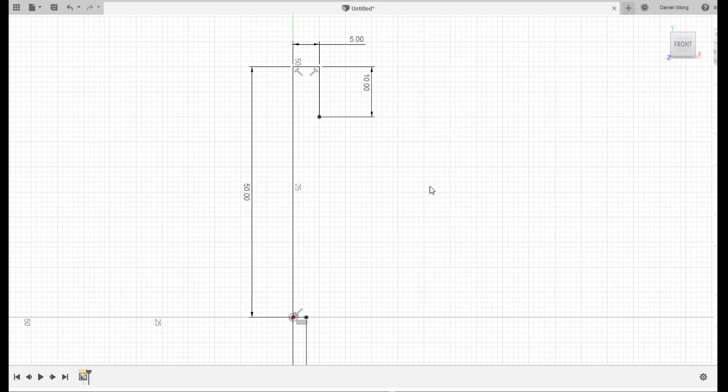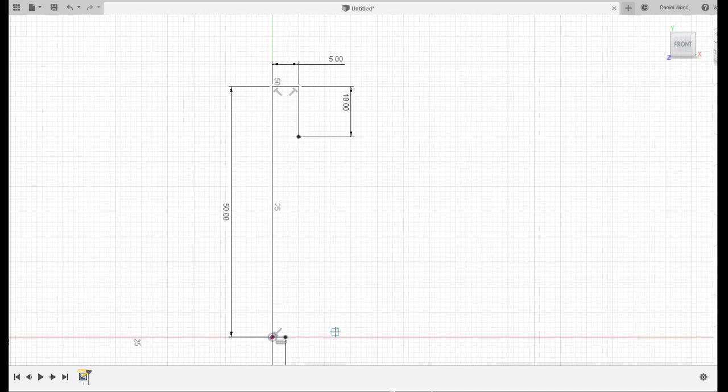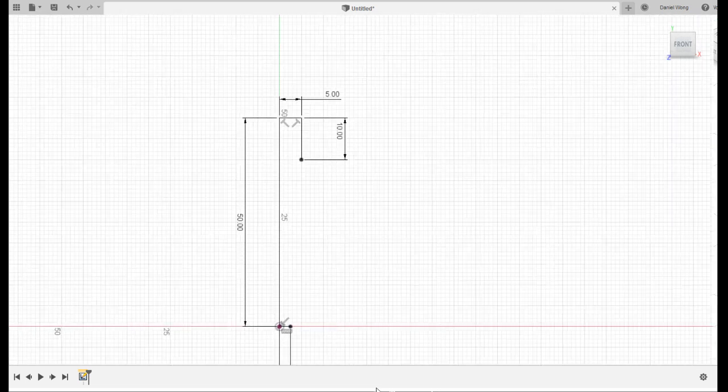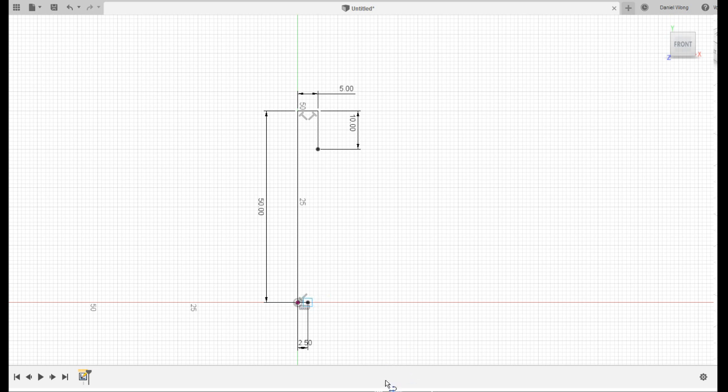The trick to this one is that you have a line that has to extend out from this corner. You have to start with an angled baseline out the bottom. That looks something like this. Then you have two circles of radius 3. So you'll set that to 3 diameter and that to 3 diameter. I'm going really quick, but I hope you guys can get it. 3 diameter. Thank you, Farhan. Otherwise that looks really tiny.